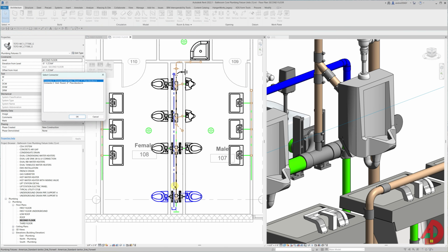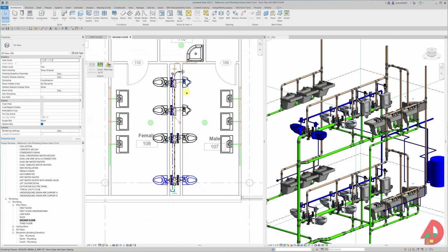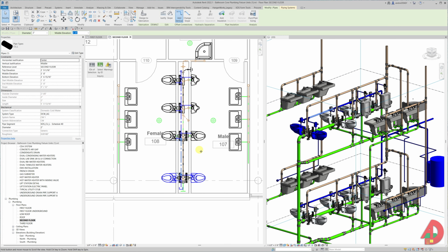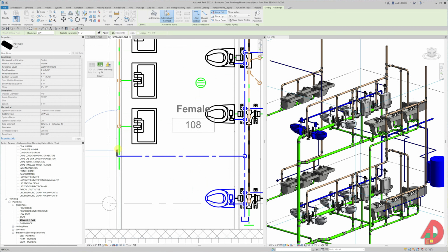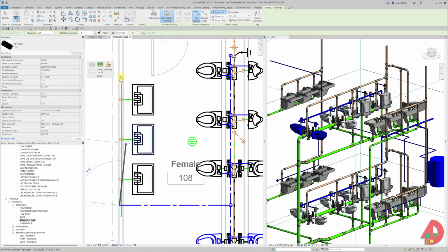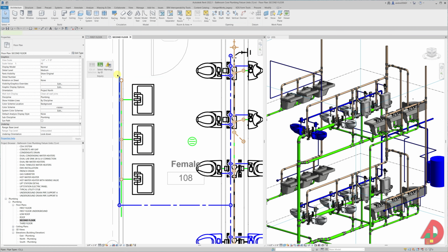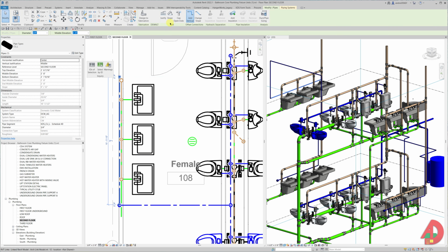If I want to get a line to the lavies, I will select this water line, use create similar command, set the diameter to 3/4 of an inch, middle elevation to 8, and I'm going to start from this other end, model a line to the left side of the view, change my elevation to drop in the wall, so I have a line to connect the lavies.